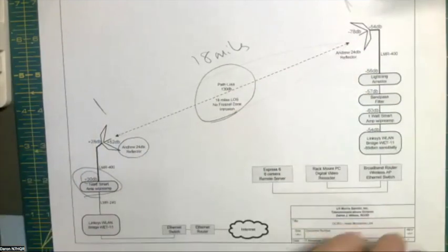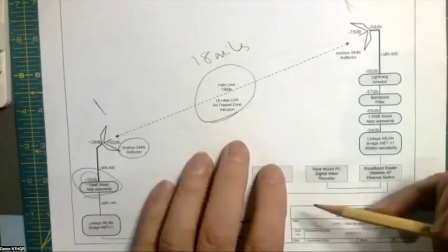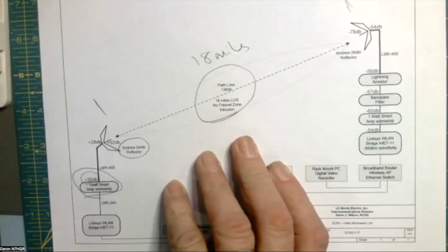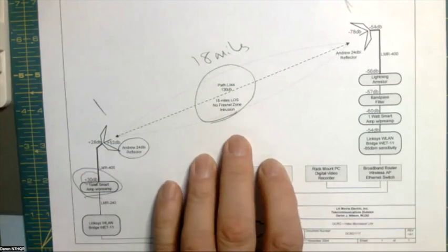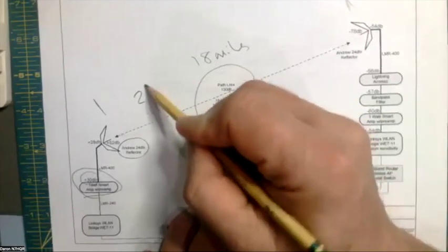Now, do you calculate that or do you measure it? That's calculated. There are lots of online calculators for that. Okay. And it's frequency dependent, so we lose more signal at higher frequencies than we do at lower frequencies. Darren, you need to explain you're working at microwave frequencies. What frequency are you at? Yeah, this is 2.4 gigahertz.